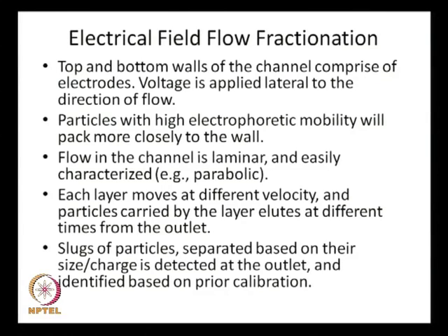Each layer moves at a different velocity, and particles carried by the layer elute at different times from the outlet. We discussed this already. Slugs of particles separated based on their size or charge are detected at the outlet and identified based on prior calibration. So, this is exactly what I said. For the time being, I want you to appreciate that these methods can be very handy when it comes to accomplishing a separation in micro devices. If you are interested in the theories, what force we are talking about, what would be the drag force, we will come to that very soon.